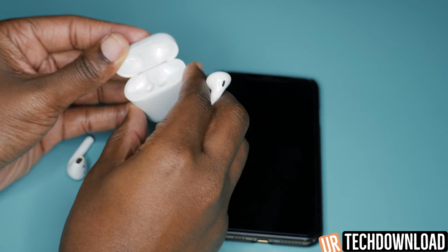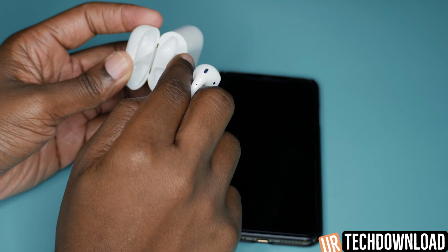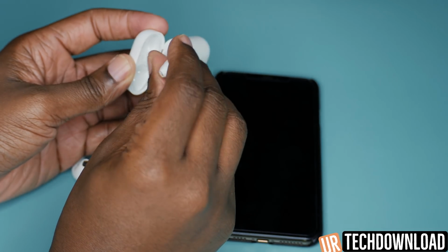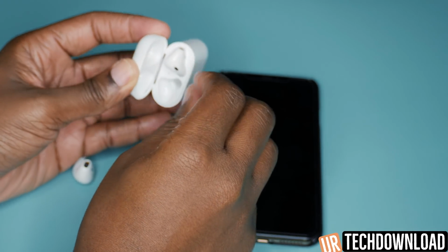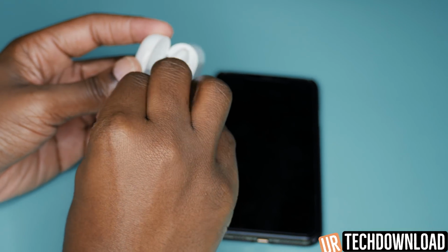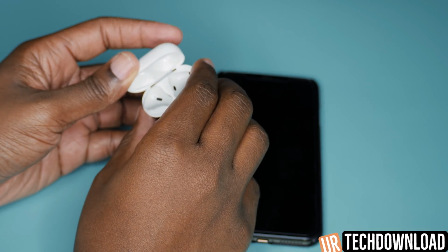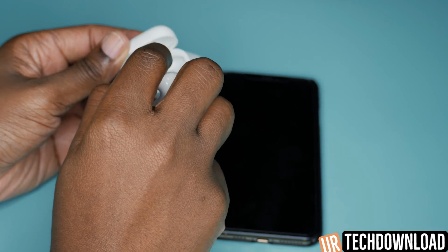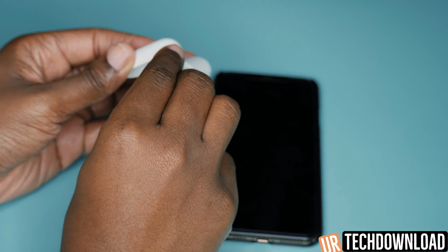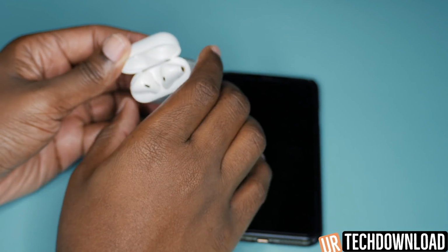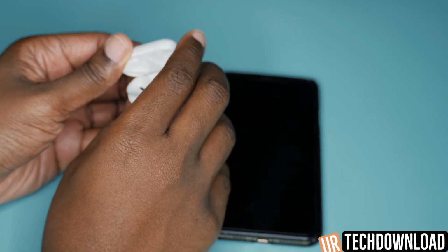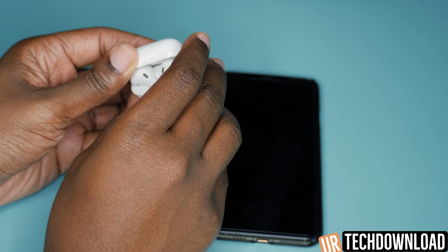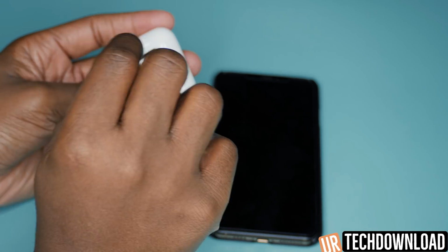If the AirPods themselves aren't charging, if you look at the bottom of the case itself, there are connectors at the bottom where the AirPods snap into place, and those need to make a connection as well. If they're not connected in fully, then the AirPods won't charge. So you want to make sure that there's nothing obstructing down in the actual case itself and preventing the AirPods from making a full connection. So those are a couple of things you can check to make sure your AirPods charge the way they're supposed to.